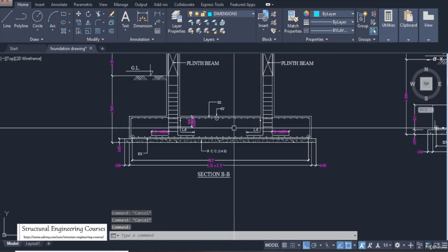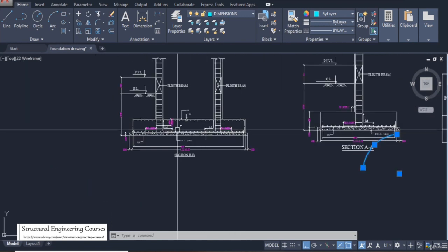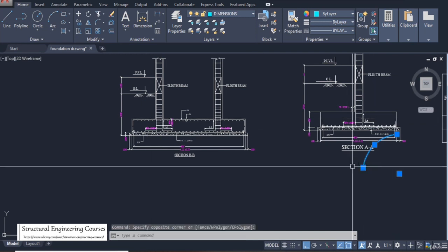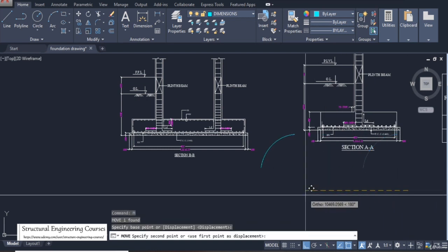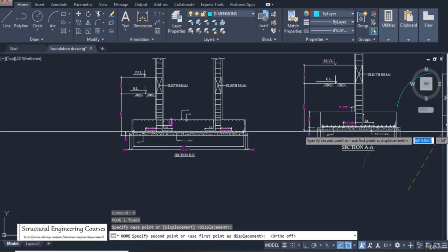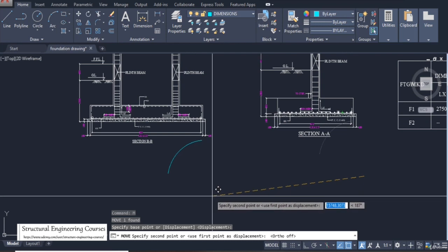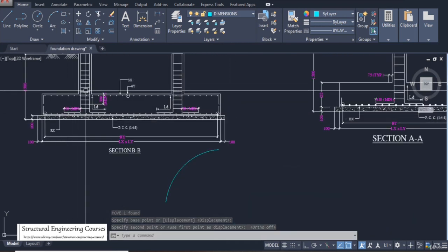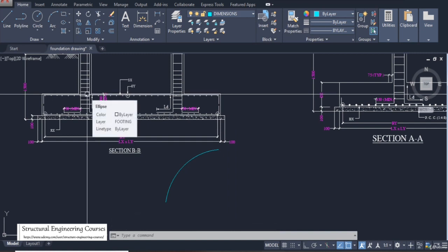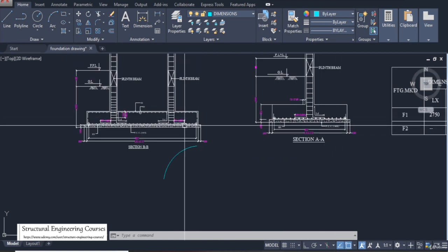Now when we are considering the combined footing, what exactly are the bending moment profiles and how do they get balanced? This is the question that is in the mind of new structural engineers. Instead of the isolated footing, where we consider the bending moment only at the bottom, now we need to consider the bending moment for the bottom part as well as for the top part. Now, first discussing the bottom part here. Basically the things for both foundations are the same.